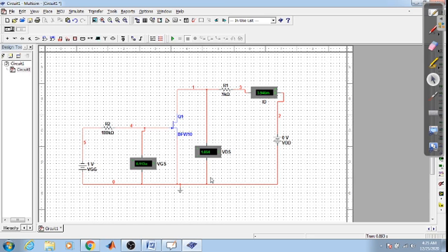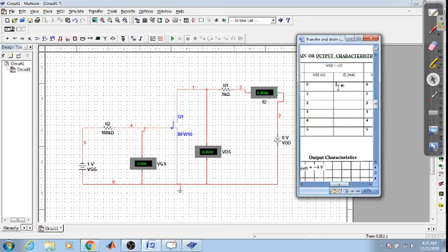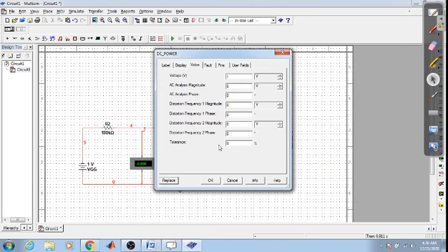So set VGS to minus 1 volt. And now go on increasing from here, and note down the VDS and ID. The same step. We start with 0. Obviously for 0 the output would be 0 itself. Next, make this as 1 and run the circuit.